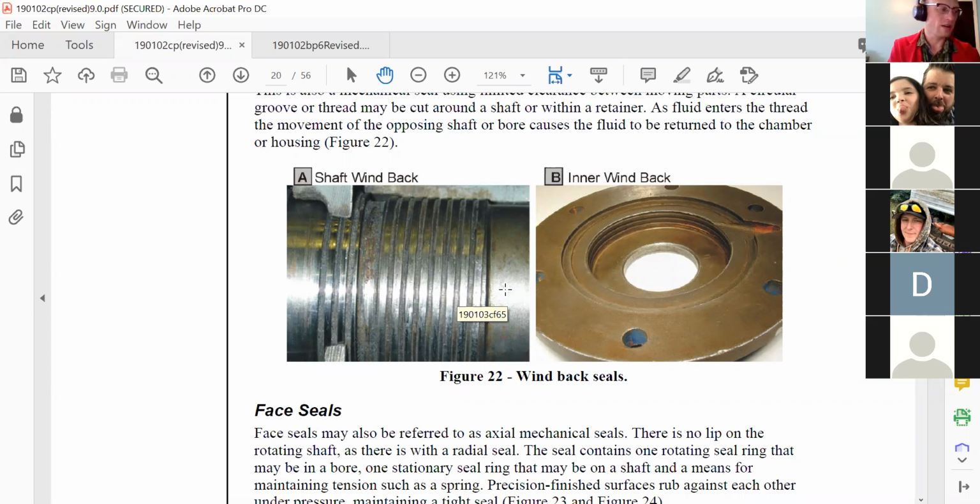We had a yard truck that would do that. A very old Mack. I think they actually still use it. But if you try and lift up a really heavy trailer, it would start to stall, and as you would push the clutch in to try and get the engine to kick back up, you'd kick it at a certain spot where the compression would come up and it'd kick the engine going backwards. Then you'd have exhaust coming out of the intake, and you had a lot of reverse gears type of thing. So, but yeah, it can happen.